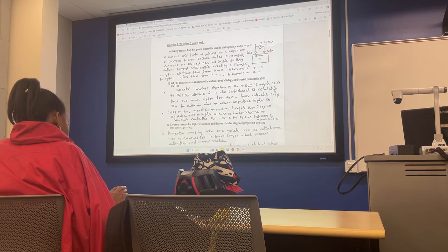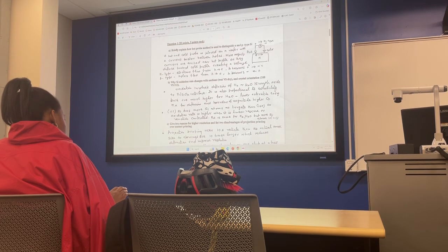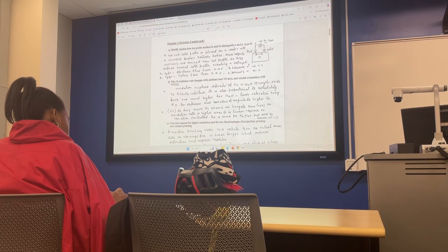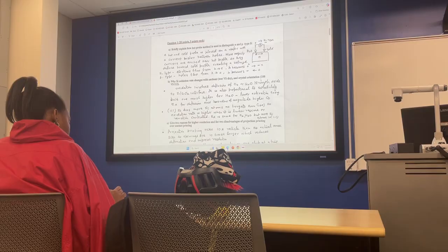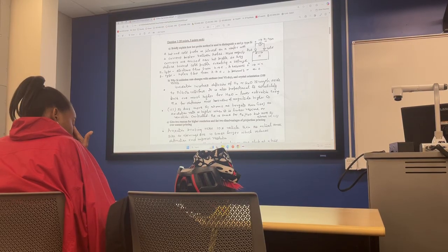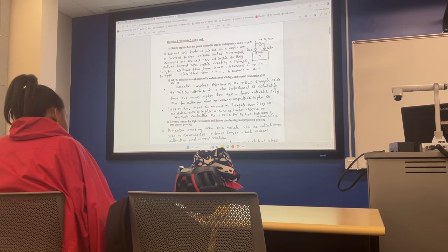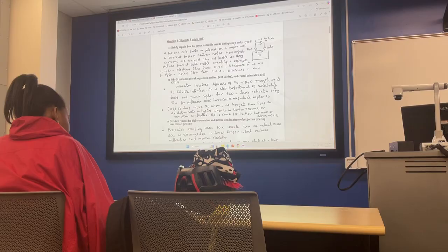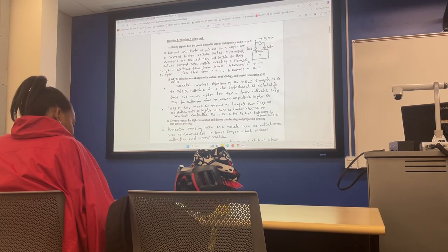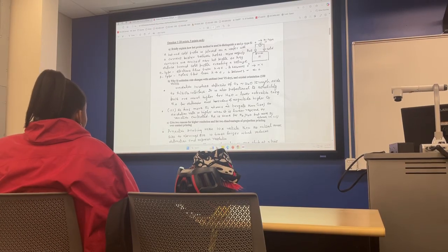Okay, then the next question was why the oxidation rate is different when you are changing the ambient from wet to dry, or when we are changing the crystal orientation from 100 to 111. So basically the answer is, as I pointed out a few times, that you have a higher solubility, which is the C0 for the H2O, and you have a higher diffusivity.